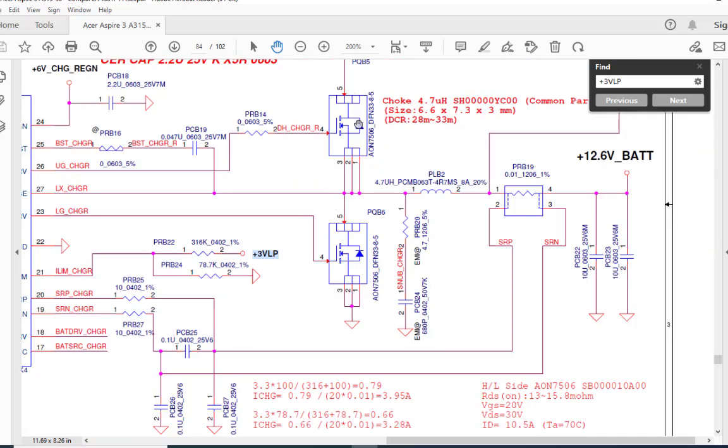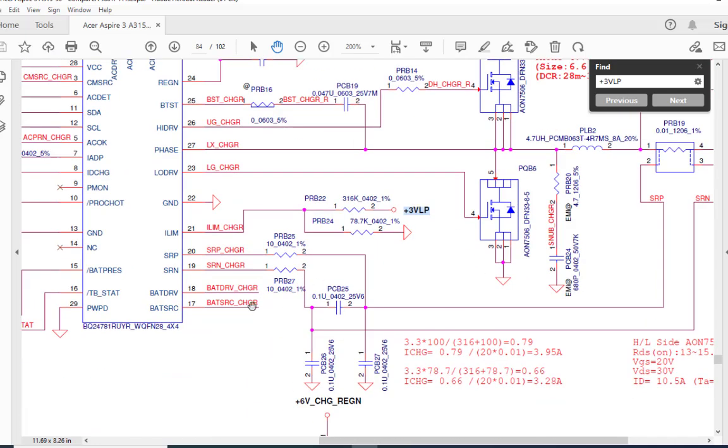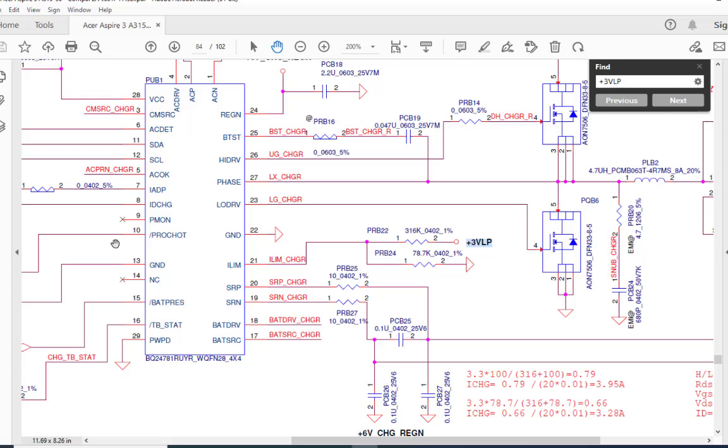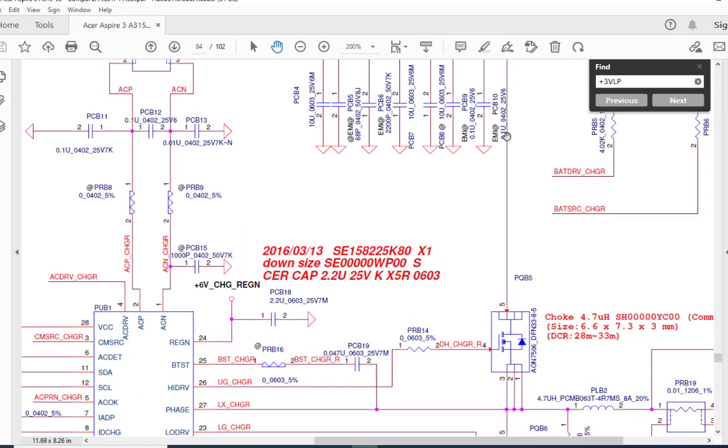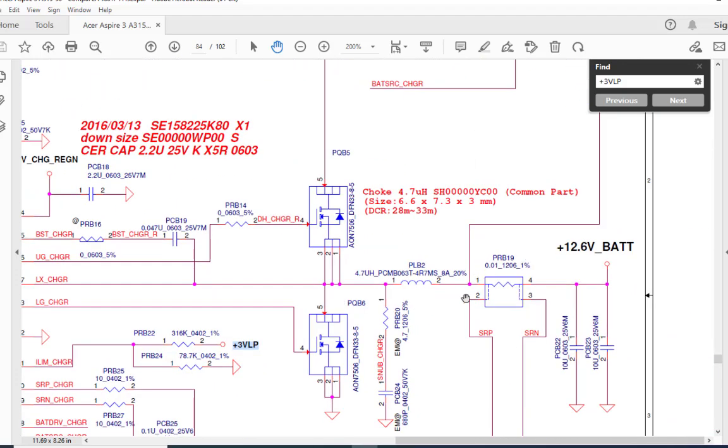And here are the two switching MOSFETs for the battery charging purpose. Both of these MOSFETs are N channel MOSFETs. When the battery needs charge, these two MOSFETs start switching, and the battery drive signals are there. The SM bus communicates, then they turn on, and here they get 19 volt, and that 19 volt starts switching. And here the buck converter starts functioning. Here is one more current sensing resistor measuring the current going to the battery and coming from the battery, and the battery starts charging.